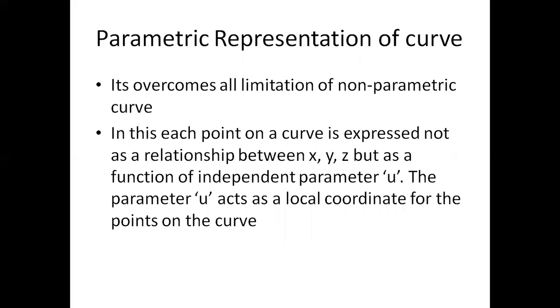Parametric representation of curve overcomes all limitations of non-parametric curve. In a parametric curve, it is a representation in u or theta. Each point of the curve is expressed not as a relationship between x, y and z, but as a function of the independent parameter u, and the parameter u acts as a local coordinate for the points of the curve.